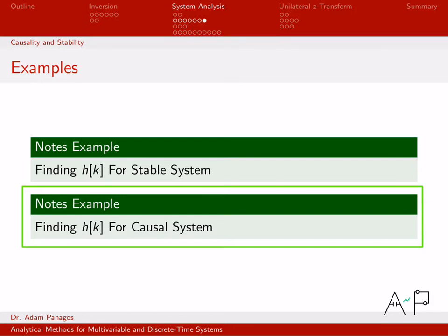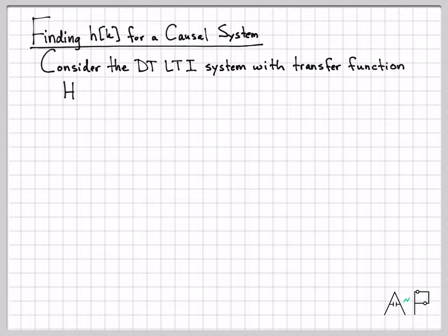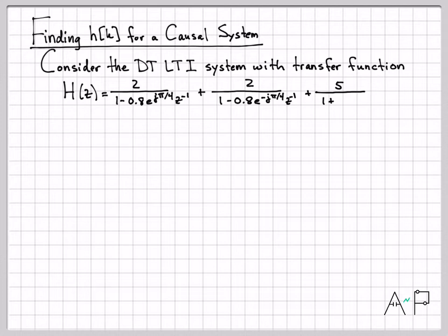So our choice for which direction we go in the time domain, whether left or right, is very simple, because for a causal system, you're always going to choose the right-sided time domain signal when you go back to the time domain. So you don't really have to think as much about which direction to go. It's always going to be the right side for a causal system. So we'll go through this just a little bit faster because you've seen all this before in the previous video example.